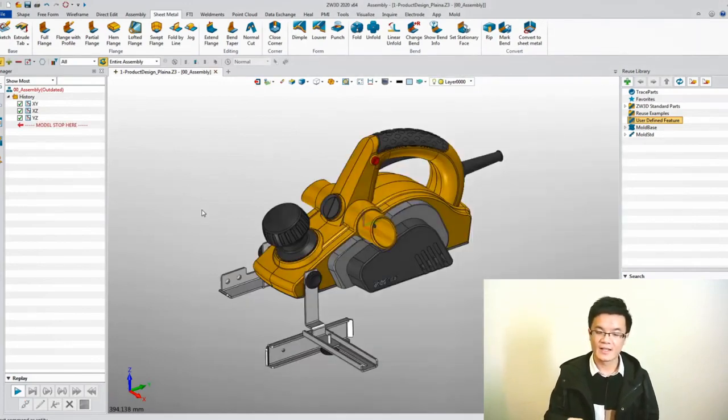You can see now I created this flange with the flange command and do the extrude cut, add the fillets and add 2 holes. Several operations can be complete in one sketch, so it's very convenient for you to complete some complex flange with this new feature.